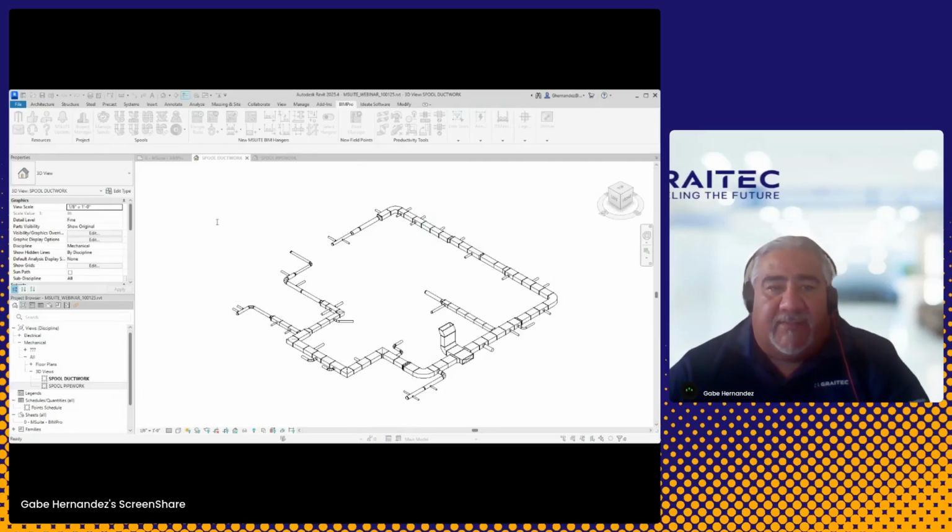But this rule, you give it a name, and then you say, look within this column here for the different types of information or data that you can choose from: properties, parameters, dimensions, custom data or fabrication parts properties, even whole categories. And what I did was I said if the ITM dimensions equal these ITM diameter dimensions, which is basically all the round stuff in here, with some exceptions. Some of these tap diameters are for my radius duct.